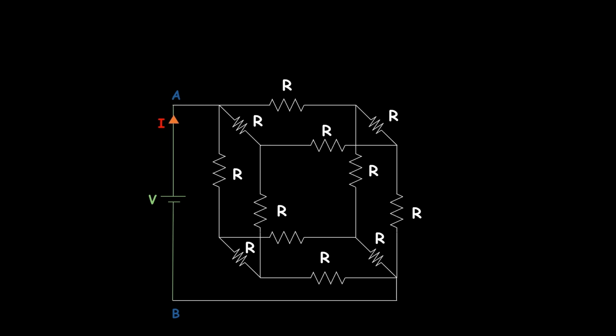As the current is delivered by the voltage source, it reaches the junction here. As the current I reaches here, it can go through these three paths. Assume that these three paths have equal resistance. Please note the point, I told you only assume. We can't say for sure that these three paths have equal resistance. If the total current returning here is I, then only we can take our assumption as correct. So for now, assume these three paths have equal resistance, so that the current I can divide equally along these three paths as I by 3, I by 3 and I by 3.